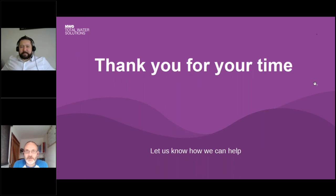Exactly right, Andy. And it's all about setting the targets and the key performance indicators as well. So in the example I gave there, the target the building manager had of 25 litres per head per day was admirable, but it was just never going to be achievable. It was never going to be attainable. Given the equipment and the usage patterns they had in that building, the 37, 38 litres per head per day they used to have was probably the natural average of what they were going to get.